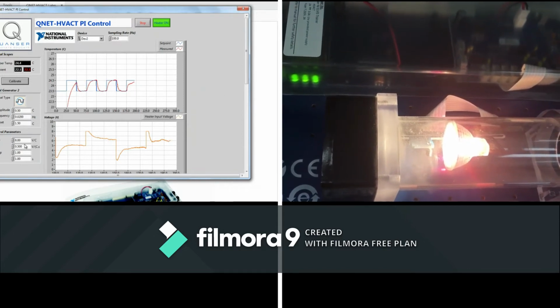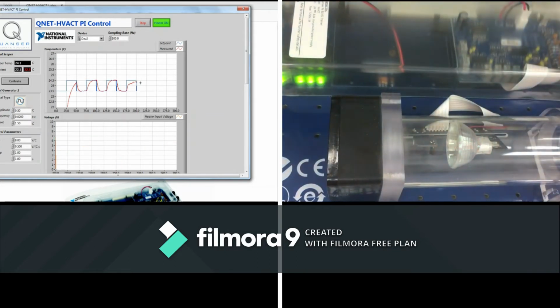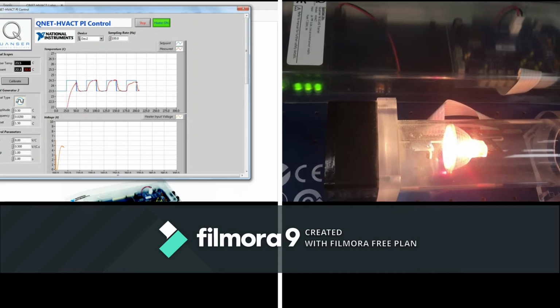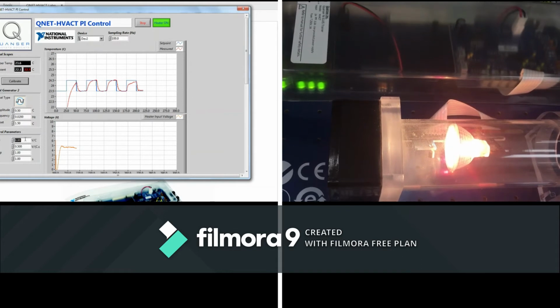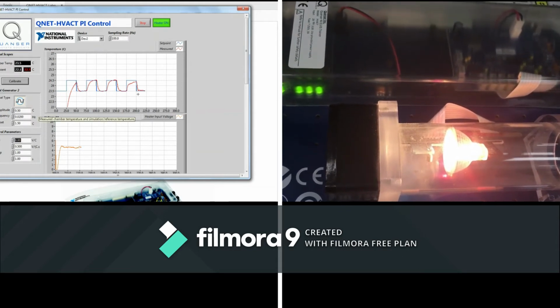So having KP higher, instead of catching the signal in halfway, we still, okay, that means increasing KP will increase the delay, and we are not able to catch the signal. The square wave is done, and a new wave will start now without reaching our value. So this is a sample of the effect of KP and KI on the system.